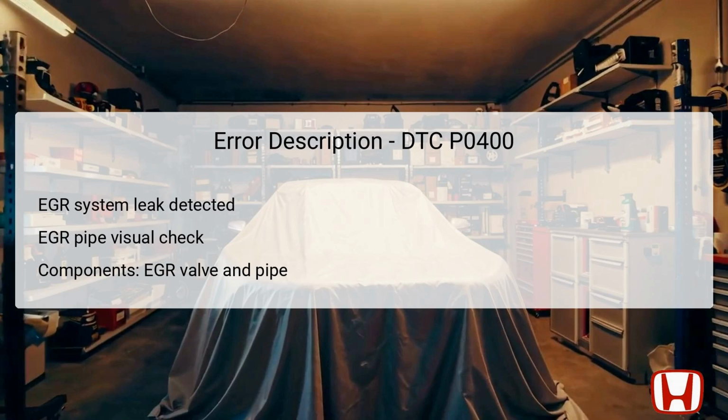Key components affected by this DTC include the EGR valve, which manages the flow of exhaust gases, and the EGR pipe, which connects the valve to the intake manifold. The EGR valve is generally located near the throttle body on the intake manifold, while the EGR pipe directs exhaust gases from the engine to this valve. Issues such as a loose fitting, cracks, or damage to the EGR pipe can result in a failure to properly recirculate exhaust gases. Understanding the location and function of these components is essential for effective troubleshooting and repair.